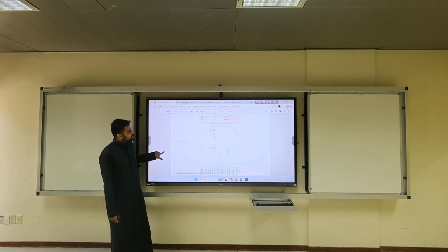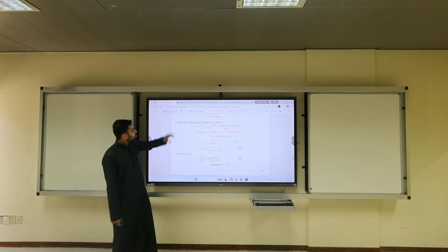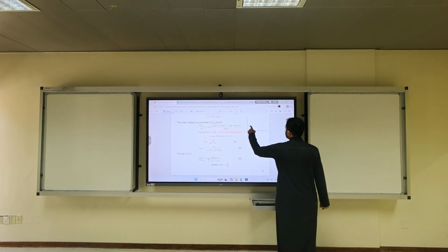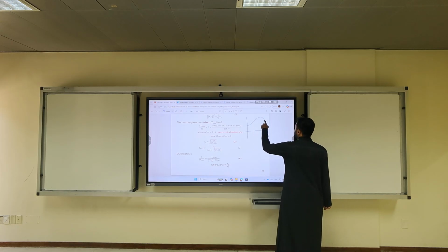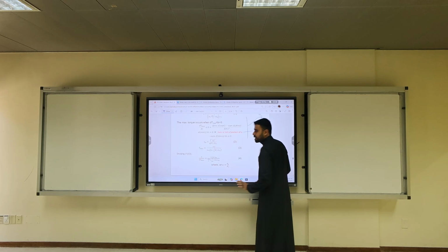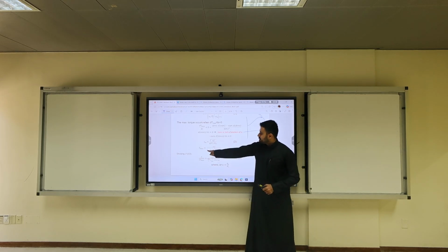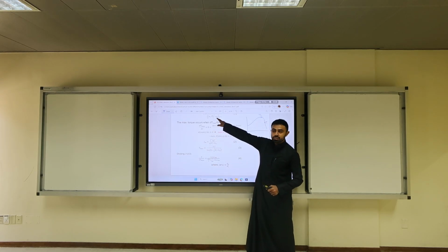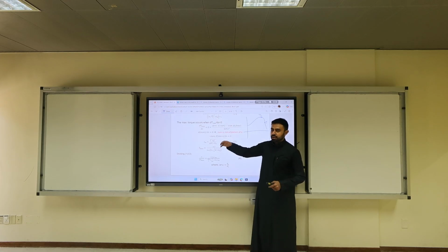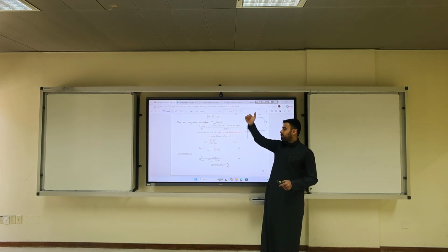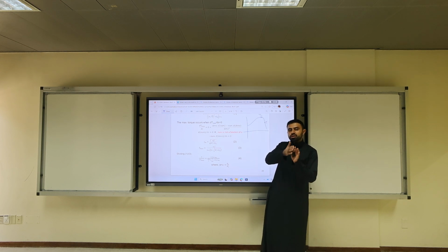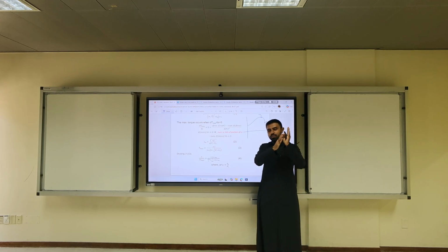Now why do we use these ratios? For example, if you have a curve, say this is class B, and let's say we want to compare T max with maybe a point T. Here we divide by 2, and don't quote me, I could be wrong, to get rid of this 2. So if you multiply by 2, this 2 will be gone. This is just a trick. So you're comparing half of the torque to the maximum torque, so instead of maybe half, you get 0.25. Now what you need is these ratios so that you can plot versus slip.